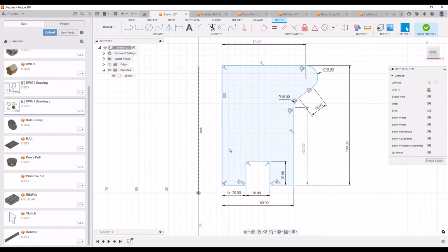Now, if you want to constrain it in space, you can see all of these little symbols are constraining it to itself geometrically. So this line will be perpendicular to this line, this line is vertical, this line here is horizontal, and so on. There are a lot of these things that we can work with, and it takes a little bit of practice and a little bit of time to work on it. But once you're there, it allows you a significant amount of control, along with parameterization in your equations and modeling. So let's put these dimensions back so that it sits in that sort of space.